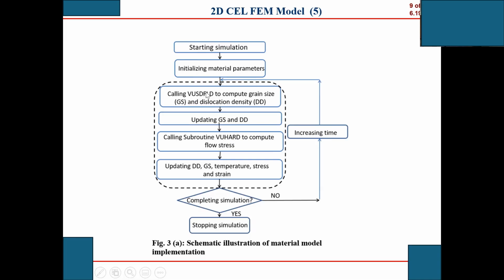This is a subroutine, and Abaqus does not have this one. You need to write this subroutine using the Fortran language, and then link this subroutine with Abaqus. Okay? Use this to call the subroutine, something like a function you use in MATLAB, to compute grain size